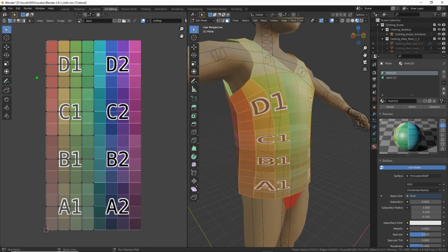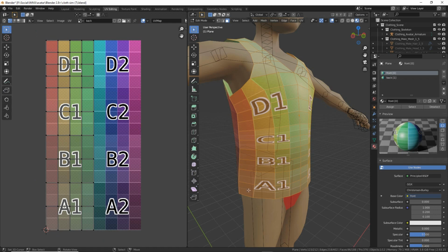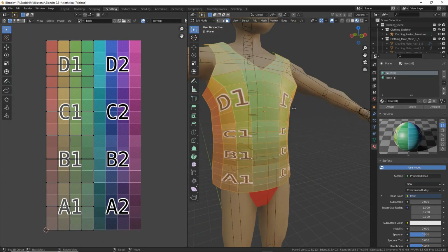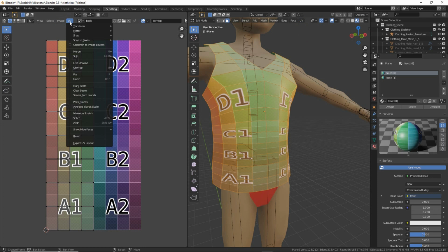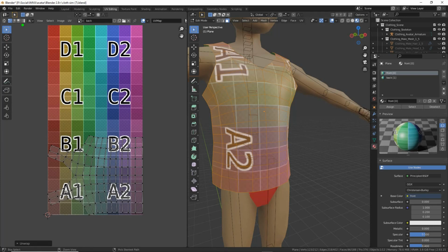UVs, and this is the default UV that was originally the plane that's now just been subdivided, because that's essentially all we did to the surface, just subdivide it. So it's kept that original UV assigned to the object, and just subdivided it. So now that we've got our selection, we can use the UV menu in the UV editor or the 3D view, and unwrap. So we're going to unwrap the UVs for this, and that'll unwrap it, and we can just do some basic manipulation.